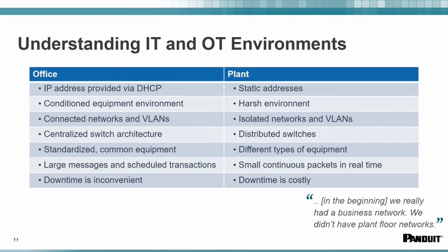In the factory, you cannot do this, so there is segmentation of these networks, and you find different control systems pretty much self-sustained, and in many instances between two adjacent control systems, you might find duplicate static IP addresses. So those could cause major havoc in communications.